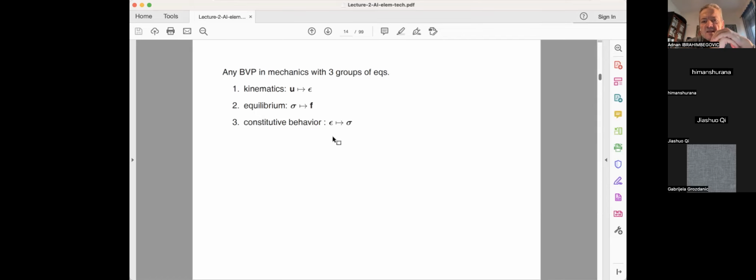Now we start with statics, so we'll start with the symmetry of the stress, so we can reduce this number. You have 3 components of displacement, 6 components of strain, 6 components of stress. So you need altogether 15 different equations. And they will come from kinematics, equilibrium, and the constitutive equation as we go along.